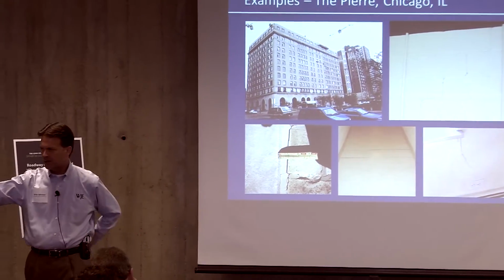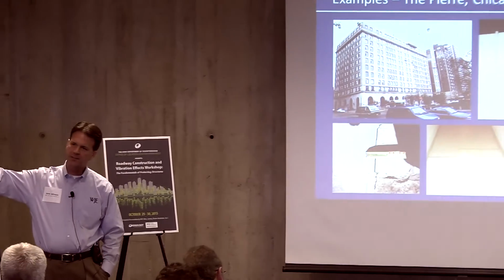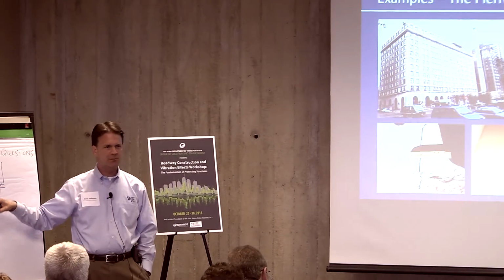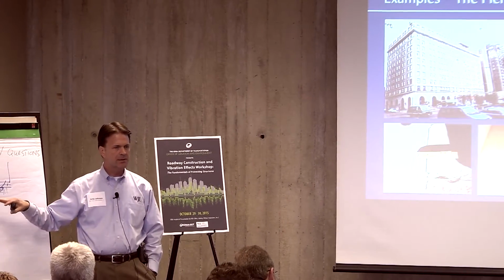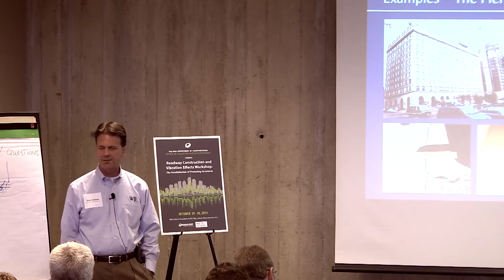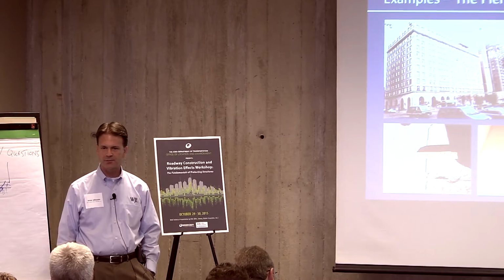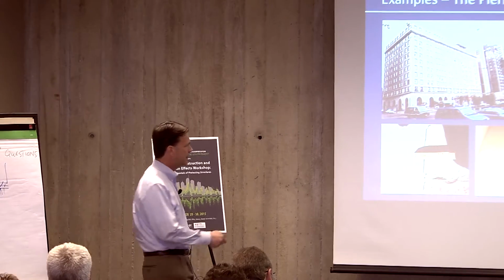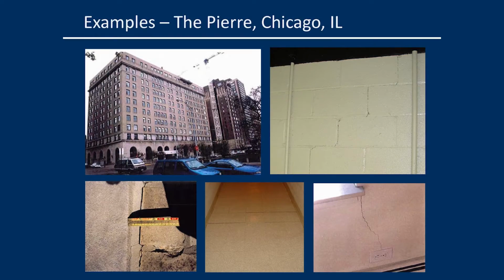It's not too unlike what I've already said here. If a building settles that much, there could be voiding, right? There could be things you need to check. So the first thing I would do is get a really good geotechnical engineer to start working with me as a structural engineer. The repair of the cosmetic damage can be pretty straightforward. This was not a listed historic property. You tuck point mortar, you fix floor finishes and drywall. So that's just one example.